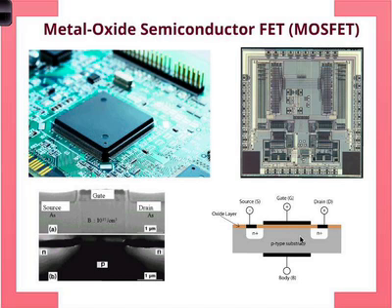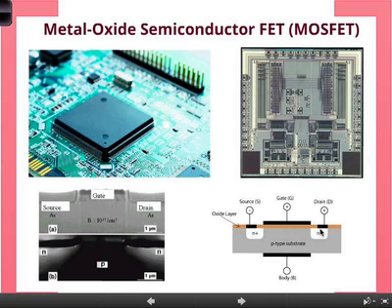Now, the operation of this device, in a very qualitative fashion: of course, you still expect a current flow between the drain and the source. Okay? This is called a drain because it's draining the electrons away. This is called a source because it is the source of the electrons. So the electron flow goes from the source to the drain, and the current flow goes from drain to the source. So exactly the same as before. But now, of course, you cannot flow through the oxide because it's an insulator. Nothing happens there. The flow happens in this lightly doped P-type layer.